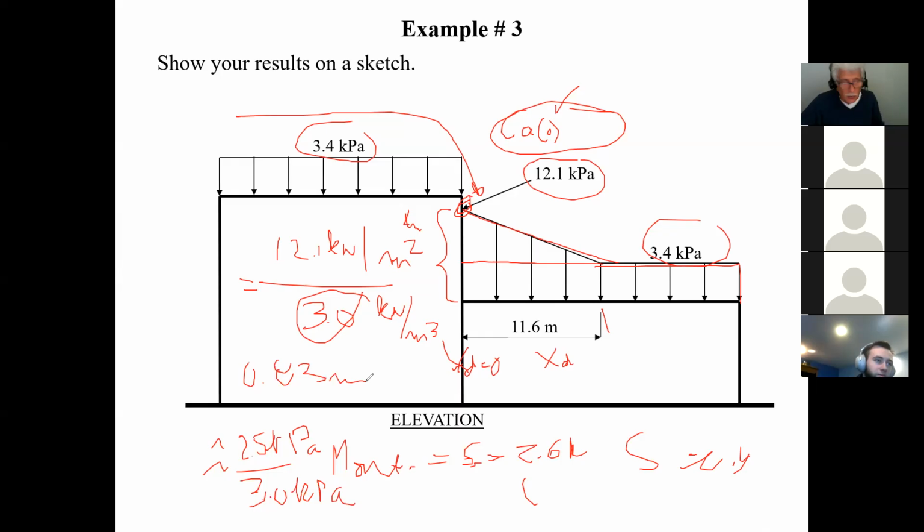Yeah. Okay. So guys, when you start seeing about a meter of snow on your roof at home, what should you tell your parents? You should probably get rid of the snow. Exactly. The reason I say 1 meter is that there are factors of safety, margins of safety built into the design of the roof. But when you start seeing 3 feet, 4 feet of snow, you should tell your parents to take the snow off your roof, especially if you're not through the winter yet.